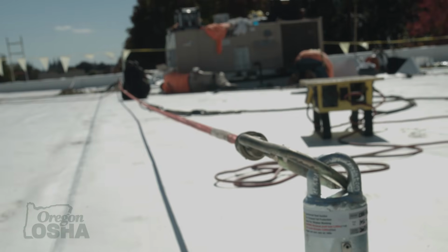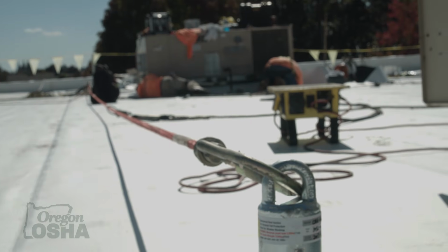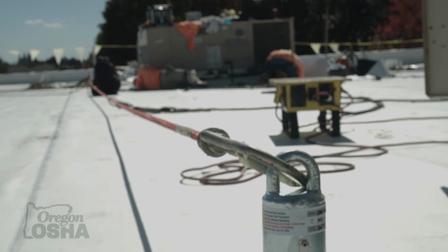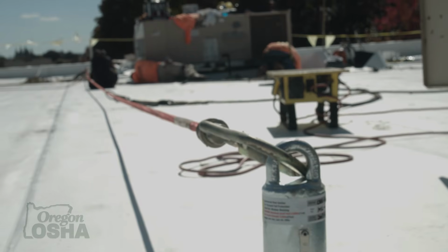It could mean an engineer, a structural engineer or a mechanical engineer who has been able to self-engineer horizontal lifelines or is able to look at the loads going into a concrete column or a wall or a form and say that yes, the way that this is situated, it can handle whatever the loads are that are going to be put into this, along with whatever else it had to support prior to that.